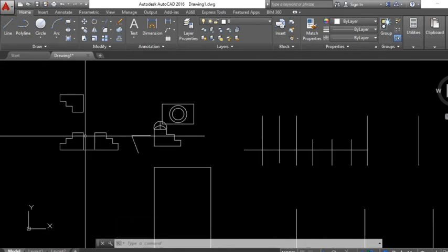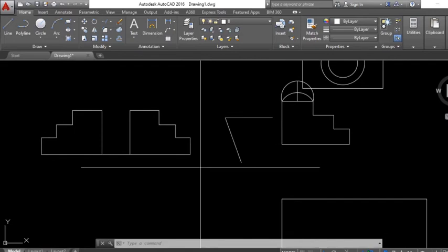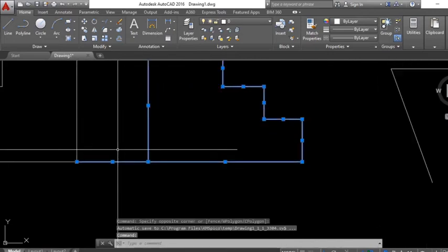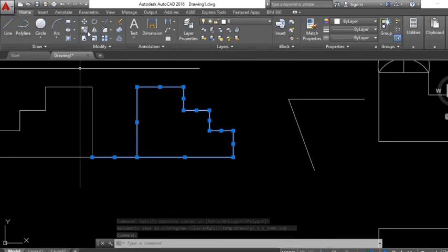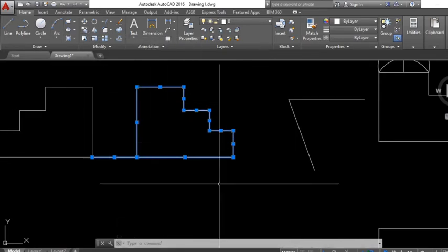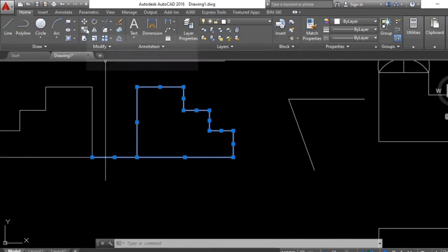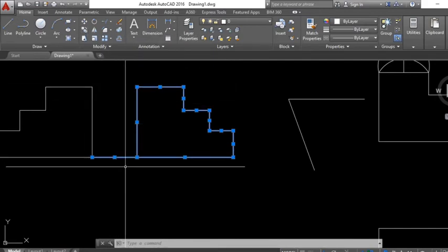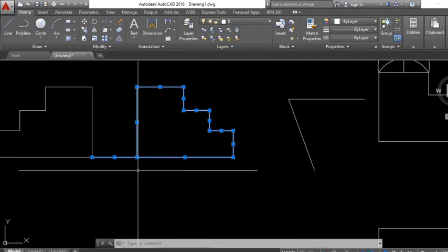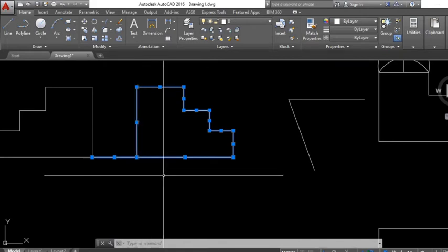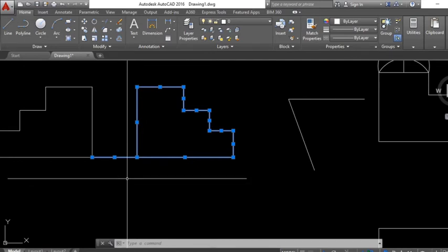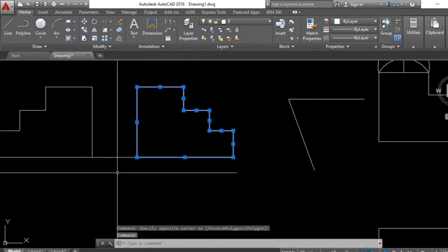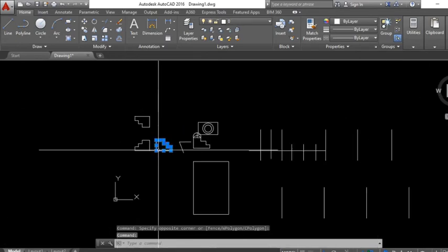Right. So let's say selecting this one and you select the baseline. Before you select the command and come and select the object, you can select the object before you select the command, any way you want. And if you want to deselect this line out of it, you can't just hit escape, because that escapes all the selection. Just hold the shift key, then drag on it or just click on it to deselect. That selection is deselected. I'm done. That's a bonus tutorial.